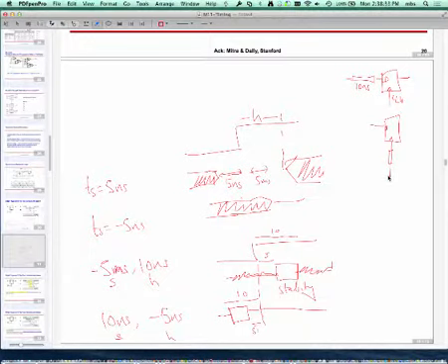So when the hold time is before or after the clock edge, do we have to change the delay of the clock? No, you don't have to change the delay of the clock. You just have to make sure your propagation delay and contamination delay of the circuits are correct. We'll see how that works out. But no, you are not going to muck with the clock.